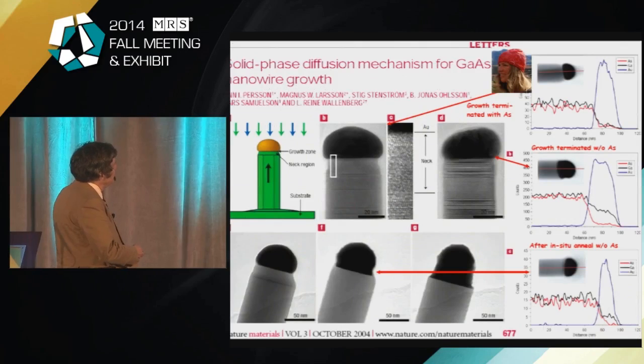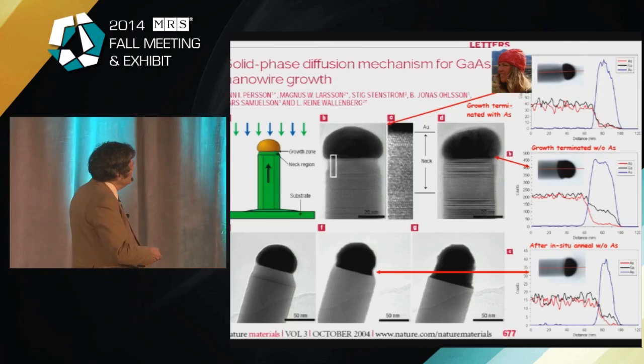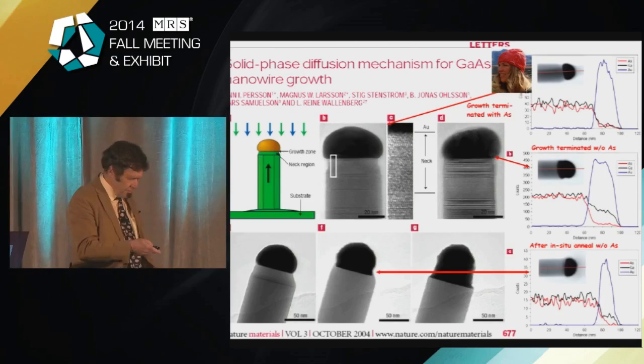So we did a lot of looking into the material science, into very much of the details. How does the composition of the gold, in this case gold gallium particle, affect the structure of the wire that is growing underneath? And how does, for instance, cooling down under different pressure conditions affect the crystalline structure and the nature of the wires?